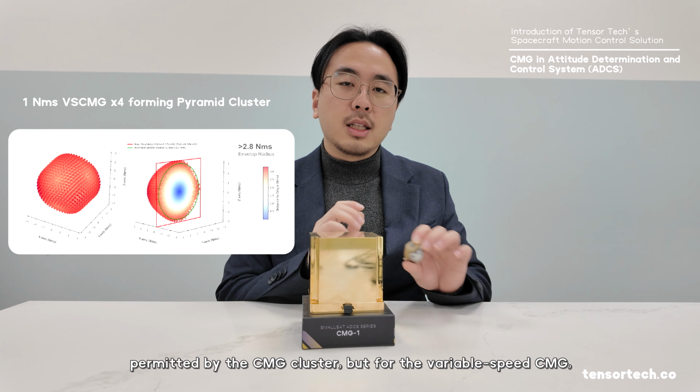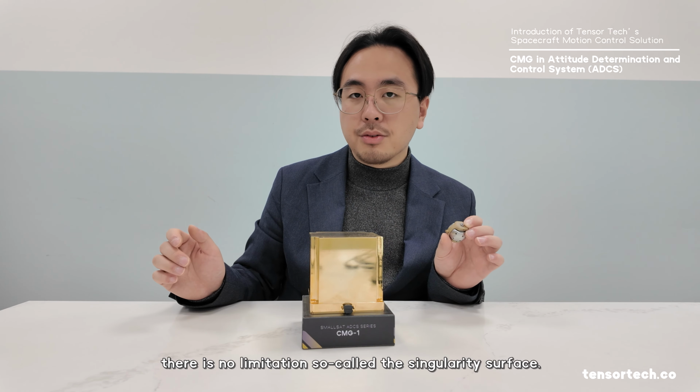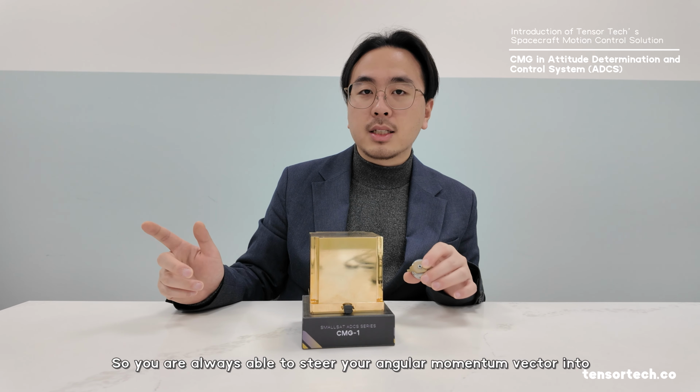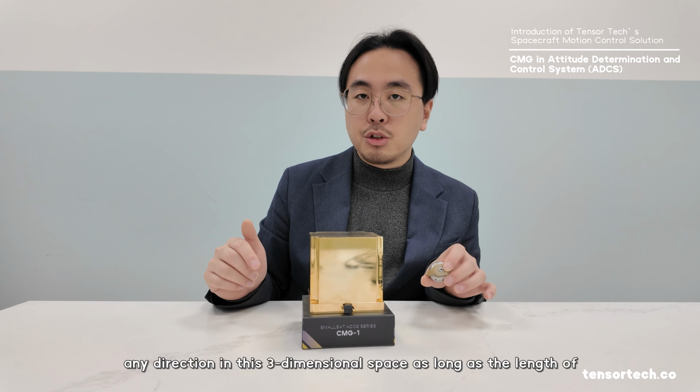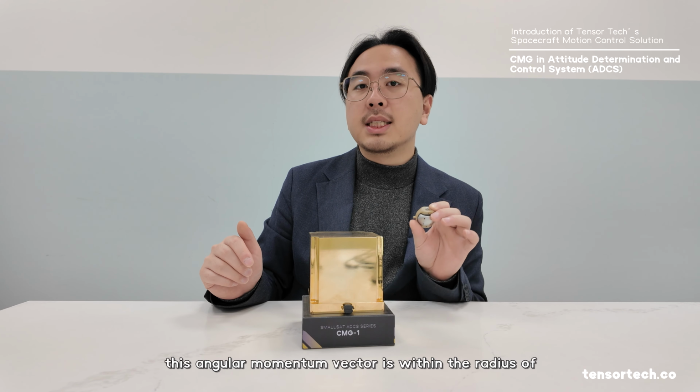But for the variable speed CMG, there is no limitation or so-called singularity surface. So you are always able to steer your angular momentum vector into any direction in 3-dimensional space, as long as the length of this angular momentum vector is within the radius of the angular momentum envelope.